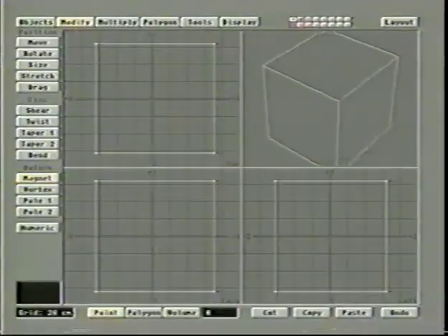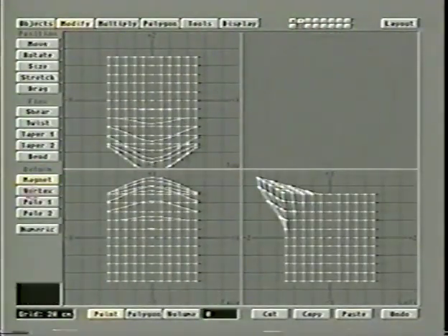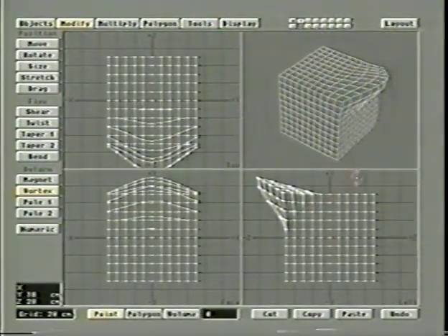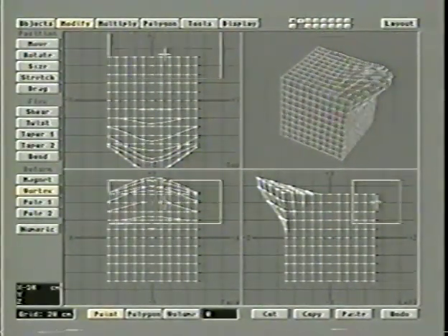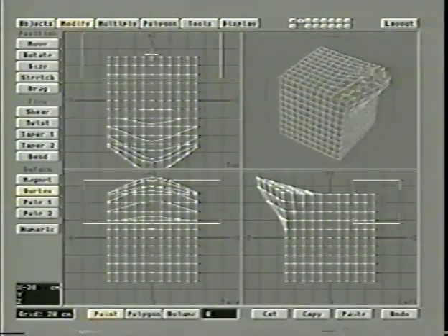Now, next tool is vortex, and vortex works very similar to magnet. You draw out with the left mouse button this bounding box area, and then it acts like rotate, because it's the second one in the menu, and it will rotate the polygons. The ones closest to the center are the ones that are rotated the most. So let's see that. We'll go back over here to our good box. I'll put it on the back corner. And let's use right mouse button here.